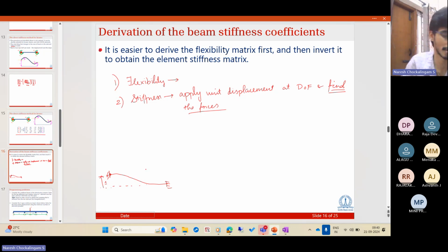It's actually statically indeterminate to the degree of 2 in plane. If you remove the effect of axial forces, it is statically indeterminate to the second degree. How do you solve this problem? Once you apply a unit displacement here, you will need to get all the reactions, and equilibrium equations alone are not enough to do it. The same applies to flexibility.